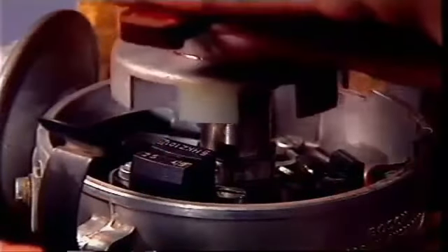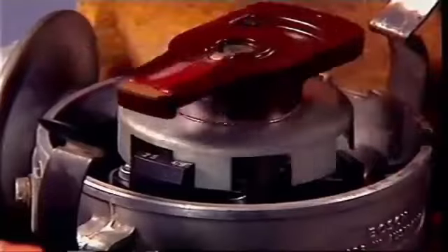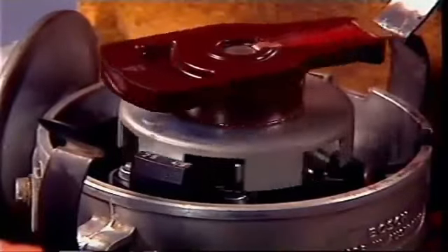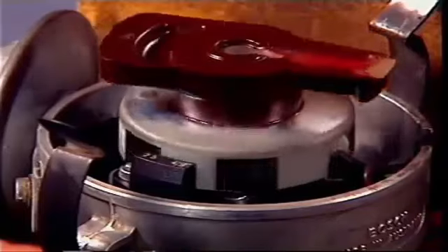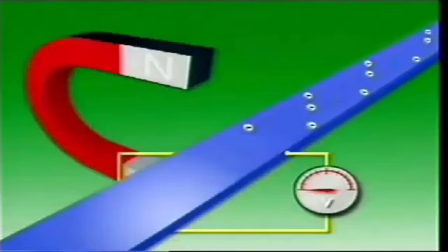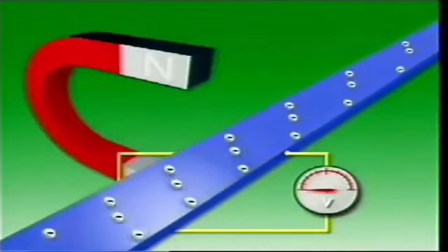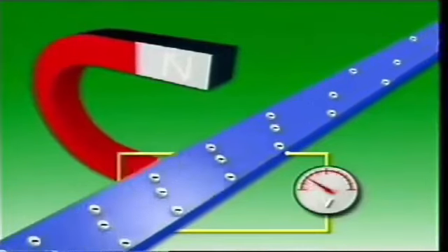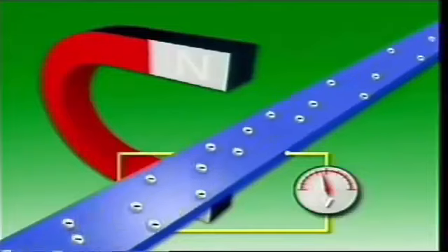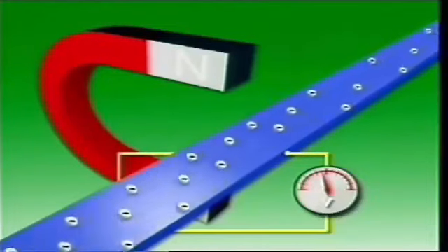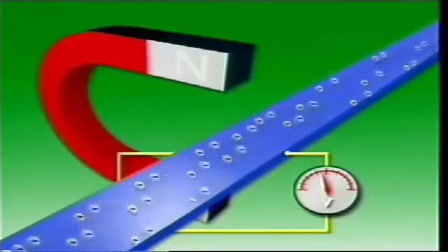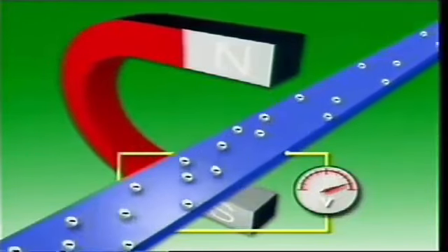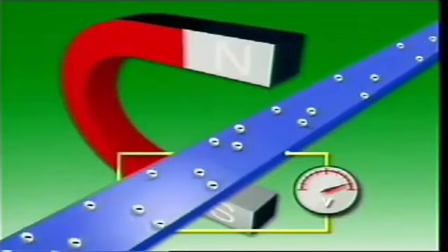Hall effect generators operate by using a potential difference or voltage created when a current carrying conductor is exposed to a magnetic field. If a magnetic field is applied at right angles to the direction of current flow in a conductor, the lines of magnetic force permeate the conductor and the electrons flowing in the conductor are deflected to one side. This deflection creates a potential difference across the conductor. The stronger the magnetic field, the higher the voltage.